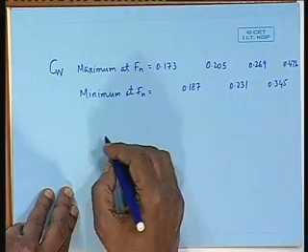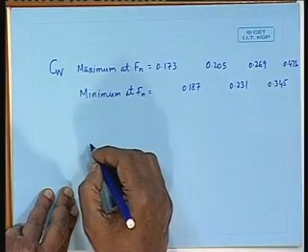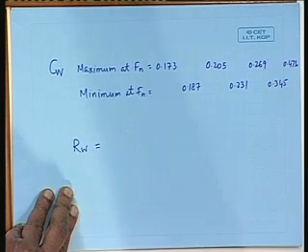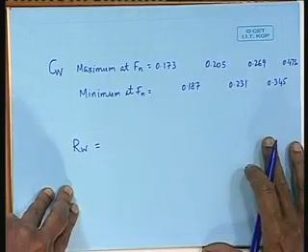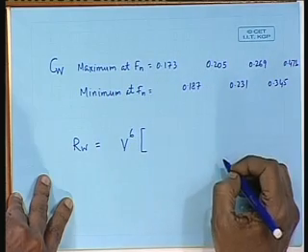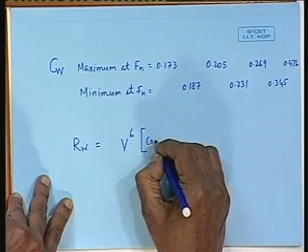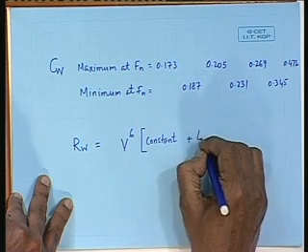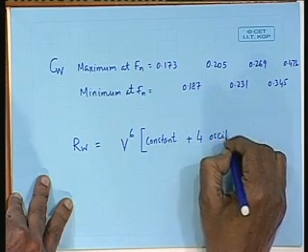So, if I write the wave resistance Rw, it has been found that it is a function of, as I had mentioned before, roughly the 6th power of speed. So, this will be some constant into the 6th power of speed plus 4 oscillating terms.